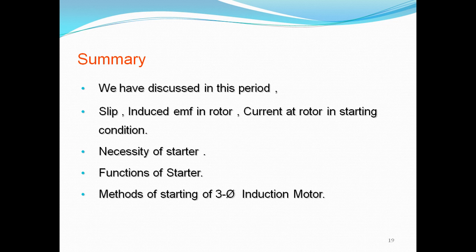Another type of starter is the star delta starter. This type of starter is used for motors which are designed to run normally with delta connected stator winding.